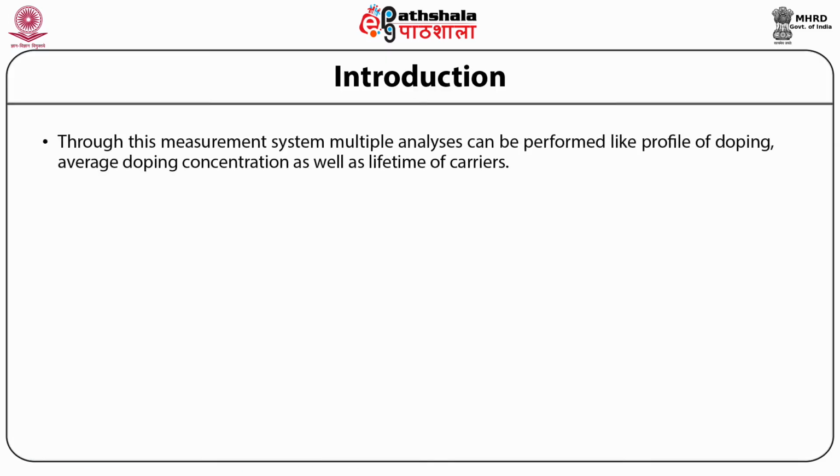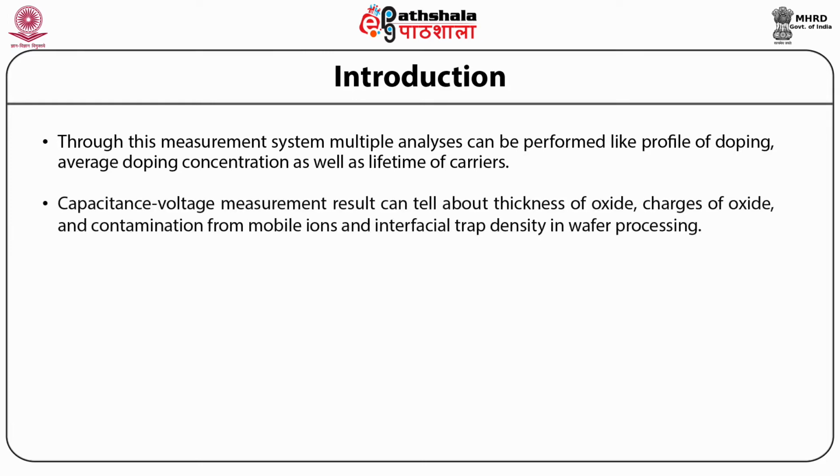Through this measurement system, multiple analyses can be performed, like the profile of doping, average doping concentration, as well as lifetime of carriers. Capacitance voltage measurement results can tell about the thickness of oxide, the charges of oxide, contamination from mobile ions, and interfacial trap density in wafer processing.